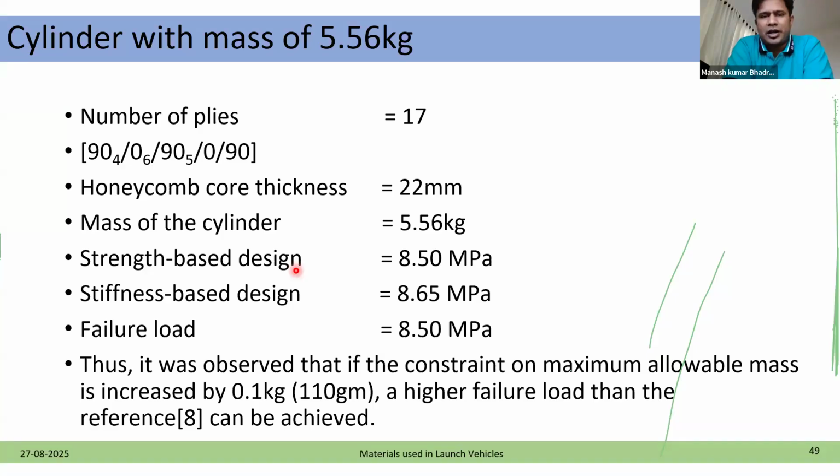And the optimization of composite structures, how this optimization of composite structure can be done without any commercial software. So if we have one evaluation method, we can couple it with a differential evolution or genetic algorithm, or for that matter any evolutionary algorithm. There are so many other algorithms also which I have not covered in this presentation. So they can also be covered with this. Similar modification can be done, like checks and loopings can be incorporated, so as to make them customized for the purpose of composite optimization.